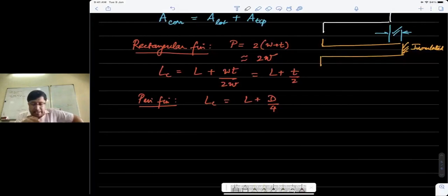The reason why having a fin may not be beneficial at all, and may actually be worse, is that the fin is made of a conductor material, but it inherently offers conduction resistance in itself. If the fin material had no conduction resistance, that would have been the best possible solution, and all the heat would just move straight out. But that is not the case. A fin offers conduction resistance, so there's an interplay between conduction resistance and how much you are conducting away because of convection.